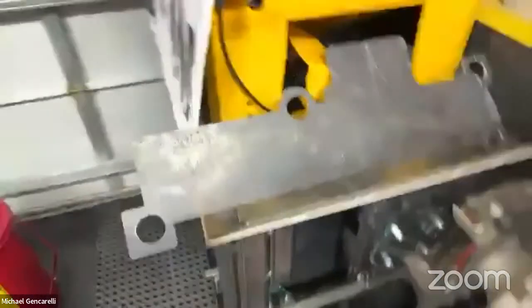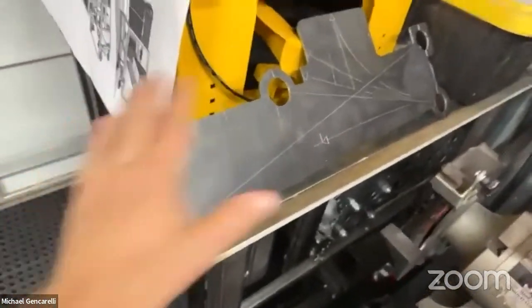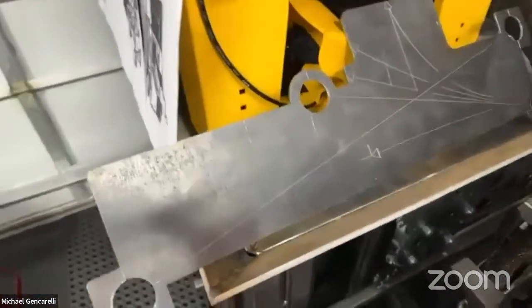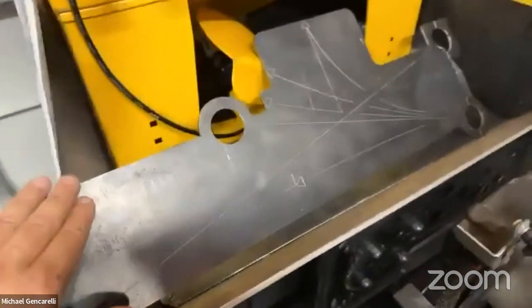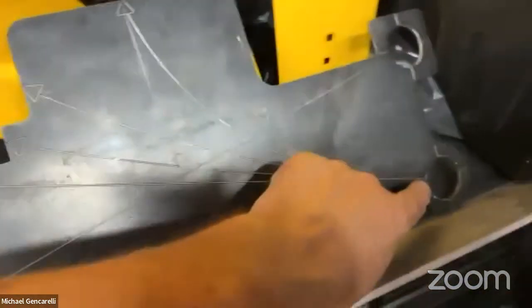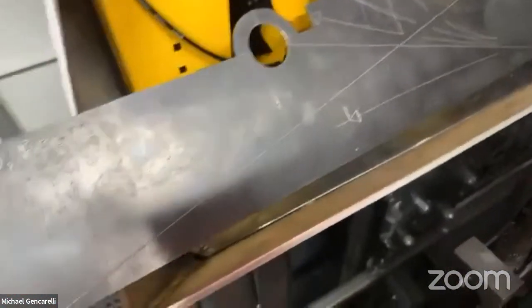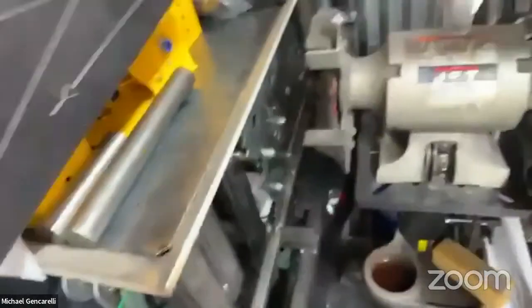Yeah, I'd be happy to share the details with you. It's no problem. And then the hardest part, because I suck at geometry, was getting all that 4-link suspension set up right. So I'm like, how am I going to measure all this? How am I going to put it all in place? Then I realized I got all the geometry. So I just needed the reference points, the distances from the holes, for the 2 different shaft lengths. So when I put this together, I made this on my plasma cutter. I put it on the shafts, and then everything was in exactly the right position, and I just tack welded it.